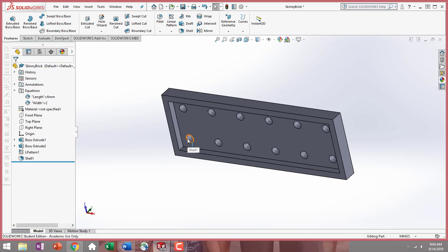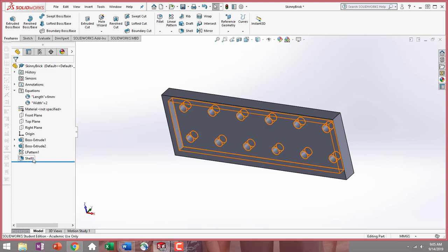Now we're going to go to step 6, where we need to adjust the depth of the hollow under your Lego by doing another extrude cut that is only 0.1 millimeters deep. This is going to be made from a rectangle sketch inside the shell base. This makes the overall depth 1.8 millimeters instead of 1.7. This is so your Lego blocks will fit together properly without cutting out too much material in your knobs.